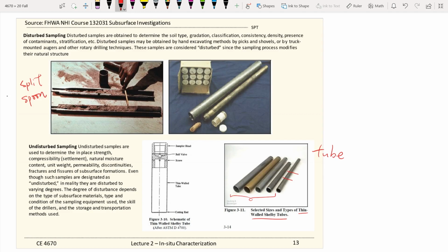They will still be intact and in cylinder form. Then you trim the soil samples down to a triaxial size, with a diameter of 2.8 inches. Those tubes are typically larger than 2.8 inches, so after you collect soil samples, you can trim them to the size you want.